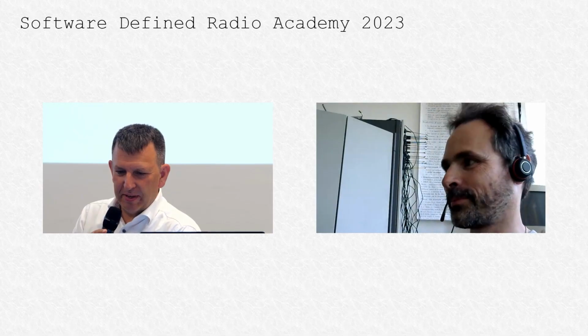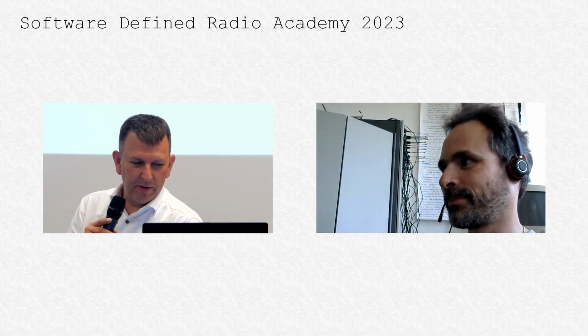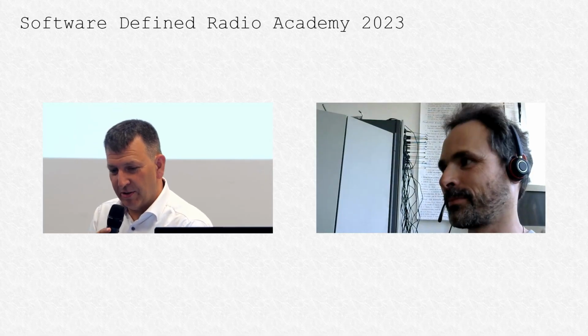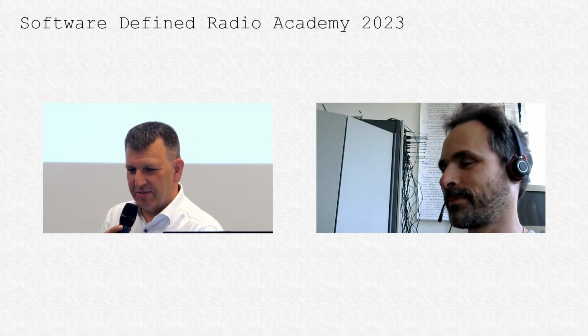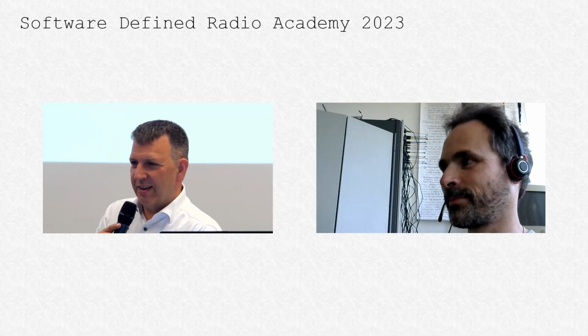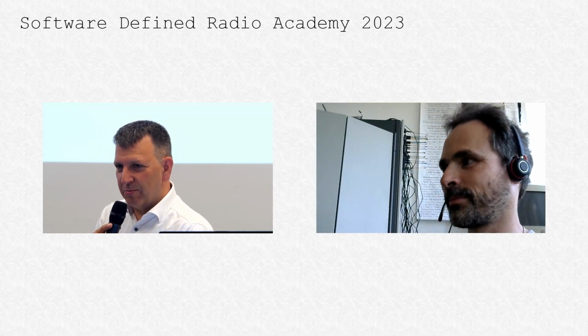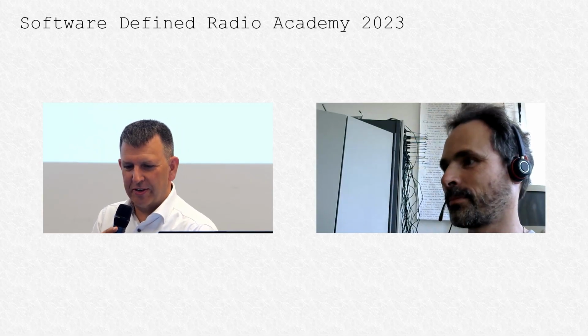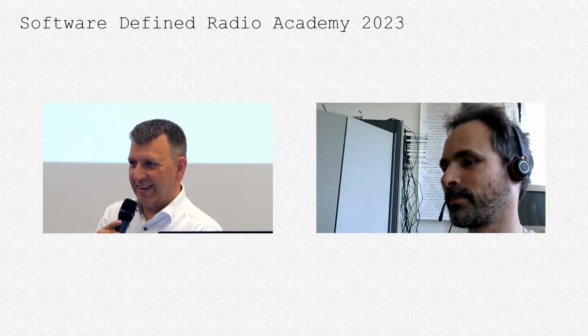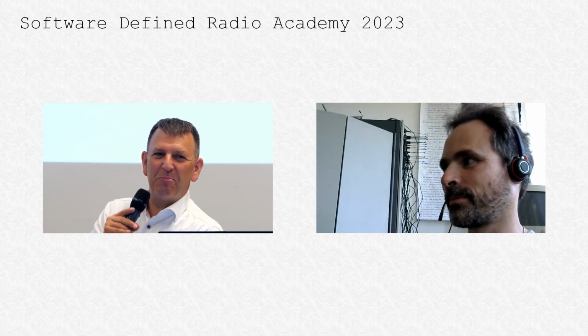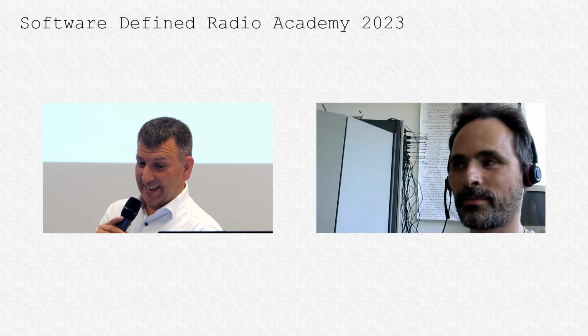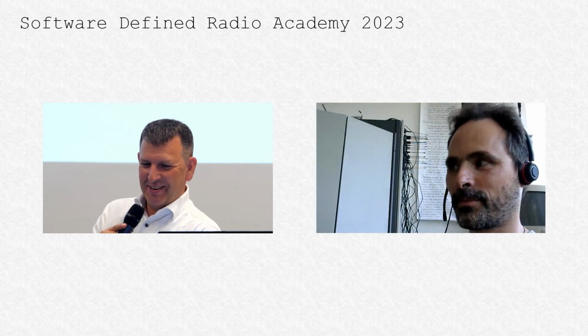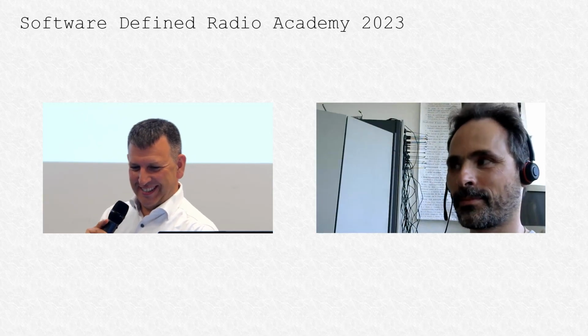Very astonishing. Very good. I have not been into such a deep research because I just have one USRP at home, and it's quite an old device, and 2 USRPs, and I don't have an octoclock, even though I did some experiments with a distribution amplifier recently. So I have a 4-fold output of 10 megahertz reference signal, but I do admit I didn't have the idea to compare them and to measure anything down there in the nanosecond range, which is pretty cool if you can do that. I cannot.